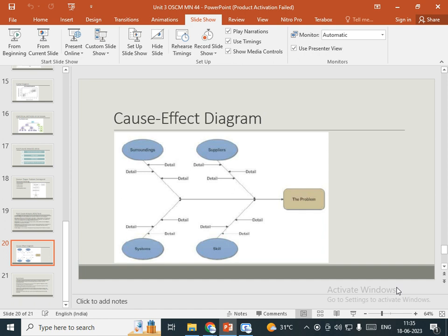So this is the first, that is the cause and effect diagram. It is also called the Ishikawa cause and effect or fishbone diagram. Most cause and effect diagrams normally consider an array of probable reasons for any issue analyzed. In the manufacturing industry, they are also referred to as 6 M's, that is methods, machineries, materials, measurement, mother nature or environment, and manpower or people. So on the screen you can see one example of a cause and effect diagram.